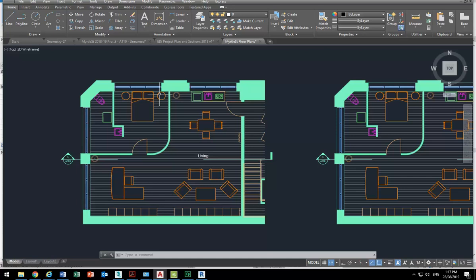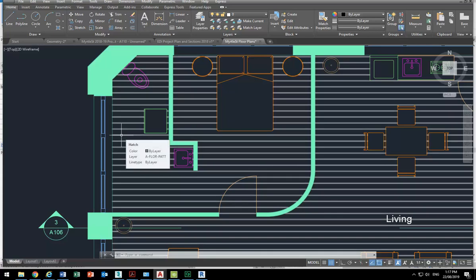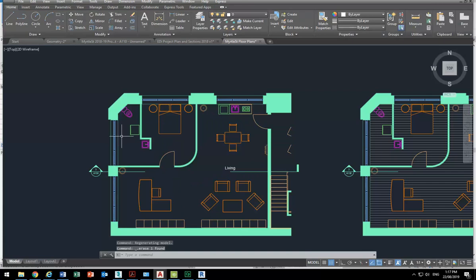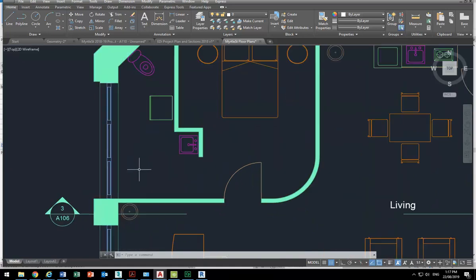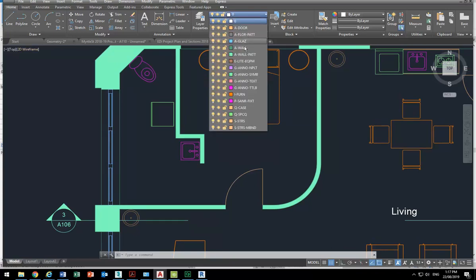But let's say we want to start to think about the risers. Now, it's also good to add in detail. So I'm going to select the floor hatch there. Floor hatch is only there if you create a floor hatch in Revit. So I'm going to delete it anyway, and I'll redo it in AutoCAD because I didn't bother putting in the tiles for the bathroom and all those things that I'd want anyway. They'll be presentation drawings, so there's a chance to convert them. So here I can just start drawing lines. You can use the layers that have come from Revit. And that's probably fine to start with, but then later, yeah.